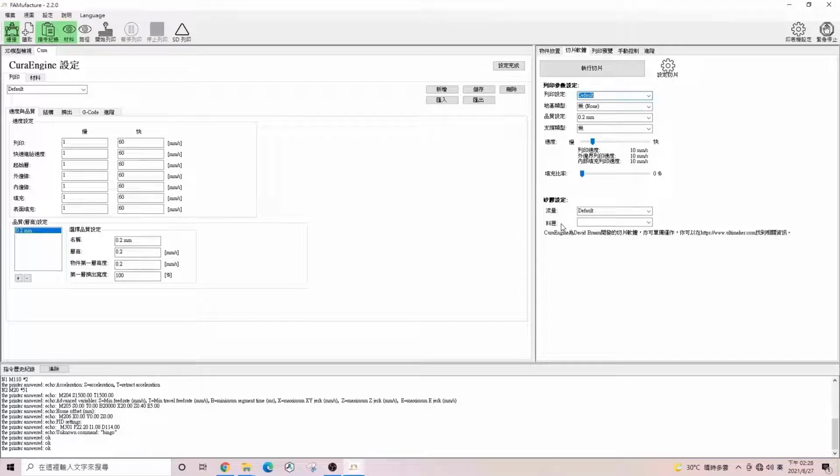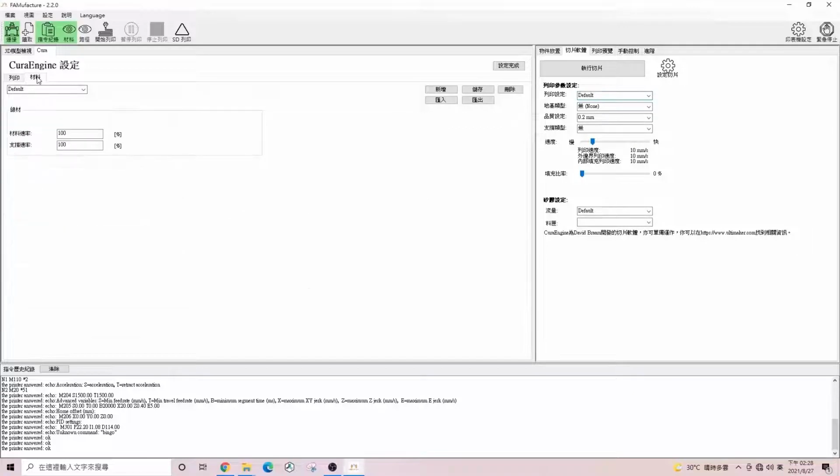There are two blocks under material settings. One is flow, the other is cartridge. Flow will correspond to material tab. Then we use default value under material tab, so the selection for flow should be default. Next, select two-part LSR for cartridge under material settings.